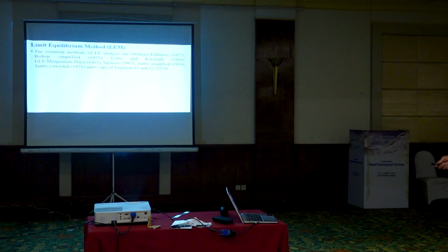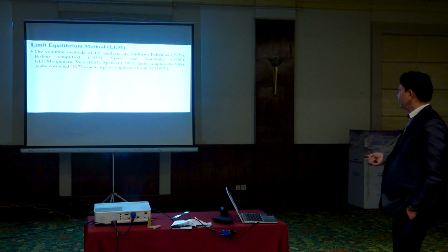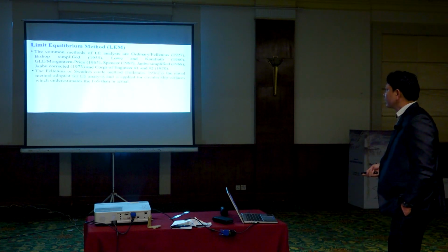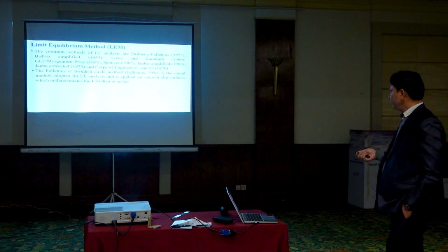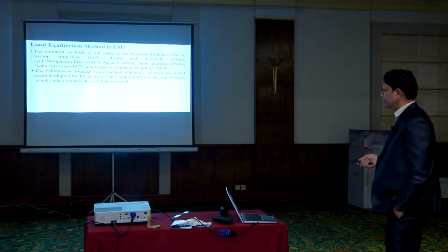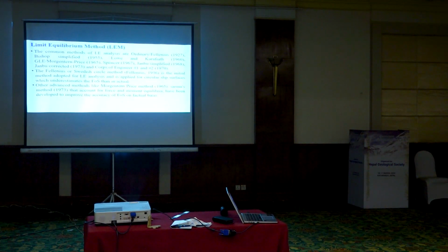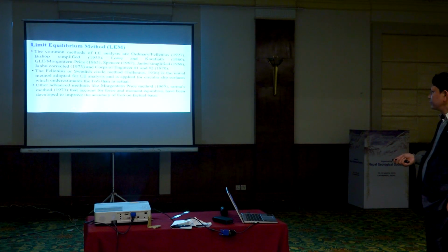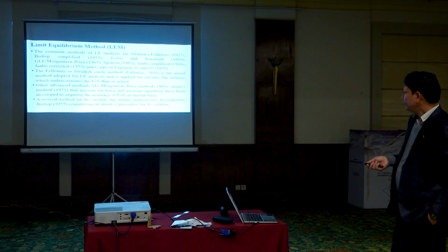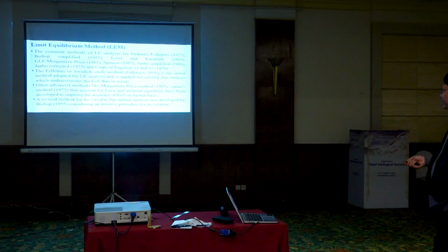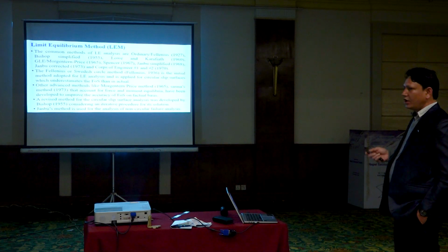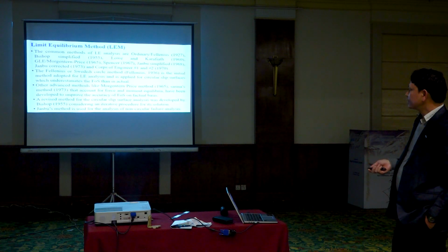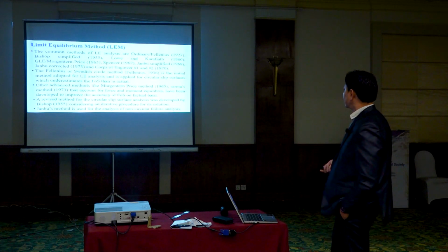The limit equilibrium method is the very basic method. In this method we use the slice methods to determine the factor of safety. Especially for circular failures, I used the ordinary method adopted for limit equilibrium analysis, which is usually used for circular slip surfaces. The other advanced methods, like Morgenstern-Price method and Sarma's method, are used for force and moment equilibrium and have been developed to improve accuracy. Another one is the Bishop method, which considers iterative solution. And the Janbu method is used for non-circular failure analysis. Sometimes the failure might be non-circular.